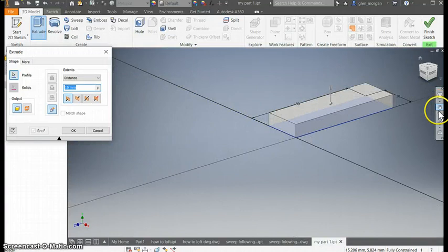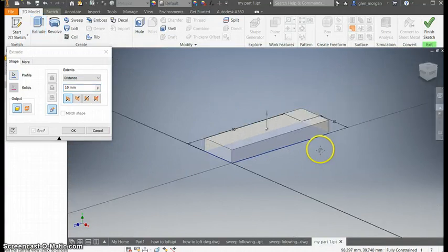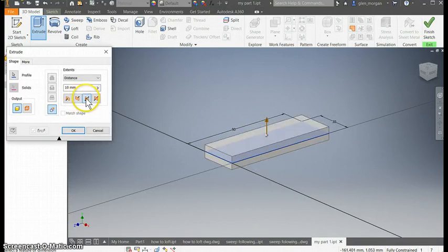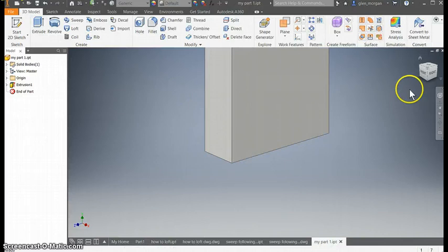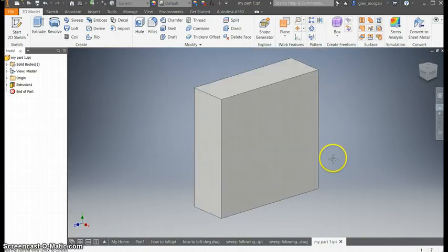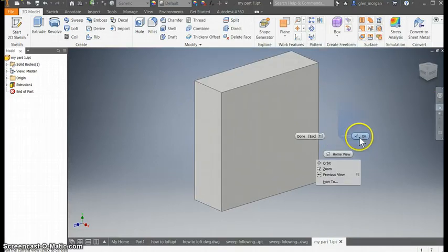We will zoom in and pan that around a little bit so that we can see it. It then gives us the option of going up or down, and you can change those. You can go either side of the line. We'll just go up, and we'll type in here, we're going to go up 90 millimeters in the case for this drawing, and we'll hit enter, and then that's done. So we can now pan that down a bit and we can see our drawing.